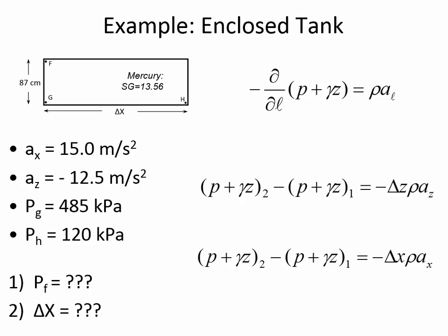It's accelerating down. Now, we're going to start using z rather than y to talk about vertical distances. Here in Euler's equation, it's using z to talk about elevation. And so the way that we're going to handle this problem is you consider each acceleration separately. And every single semester I teach this class, and I've taught it more than a dozen times, someone tries to combine both accelerations together and solve it in one step.